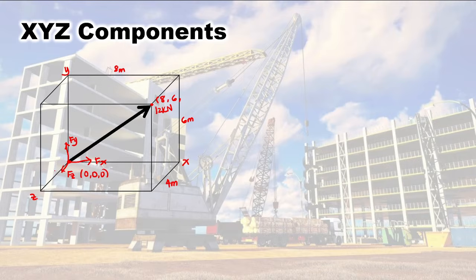The z going to the front is positive also, so 4. We already have our coordinates. Then afterwards are our delta x, delta y, and delta z. Now, how will we solve for that? Our delta is head minus toe.